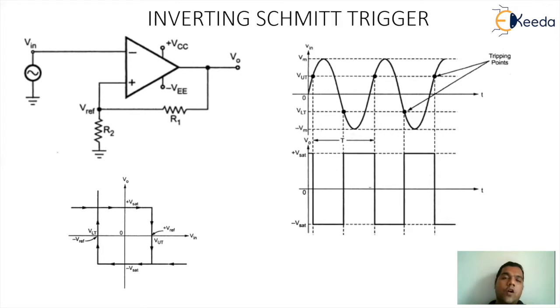But if the positive feedback is not there, the reference will get compared with noise. And under that situation, noise by definition is a random energy and has a fluctuating behavior. So because of this, it will lead to unwanted flickering of output. So to give stability to the op-amp as comparator circuits, the Schmitt trigger circuits were designed, which are basically working like closed loop comparator circuits. So these are circuits where the op-amp will be connected in positive feedback mode.